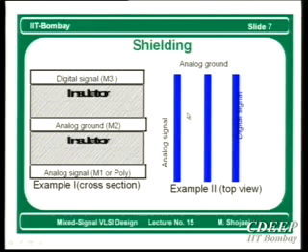Now, if I have to drive this interconnect, I make a small driver at the output of that module, and I assume that whatever additional parasitic capacitance I will have here, I will add to that driver. There is no other way. This is actually what we do. Local drivers are always used for all local interconnects. And of course, global interconnects will have them too, but for local interconnects, as long as the signal is of importance, they will have their own local drivers.